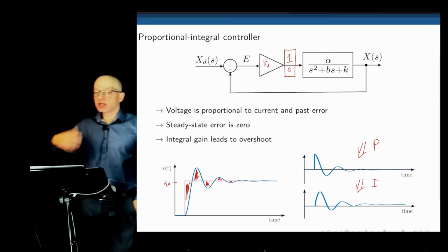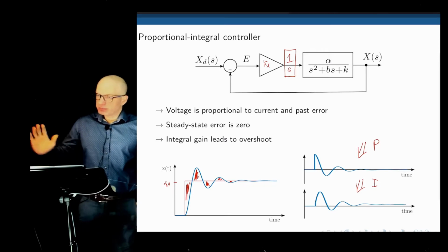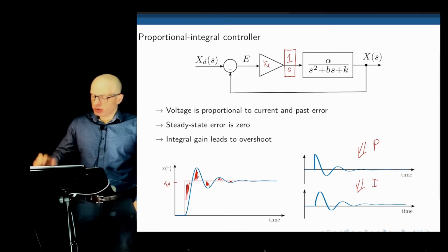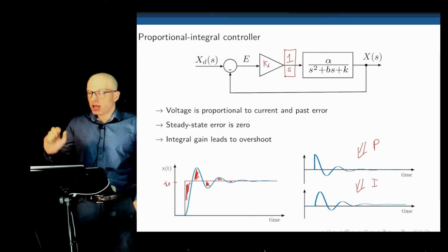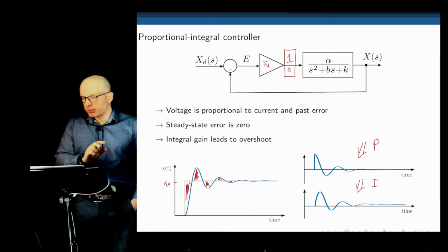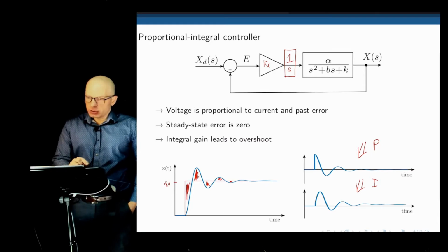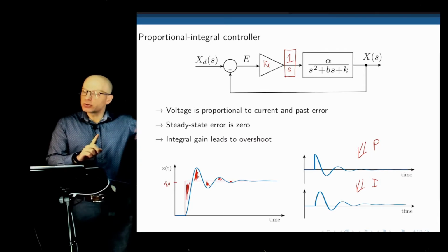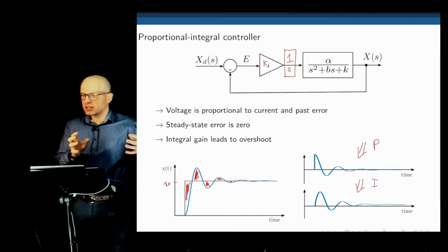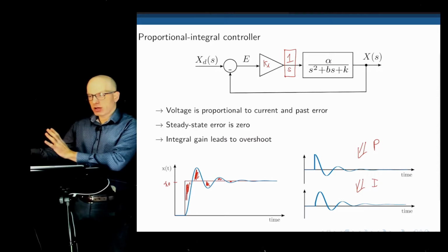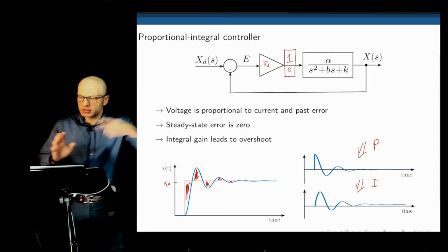Right? Because you're now taking the integral of zero. We build up some control action. We added all these areas together, and we ended up with a non-zero value. When the curve reaches zero, we just keep adding zero to it, right? So the steady state value is never zero, it is everything we calculated in the past plus this 0, 0, 0.